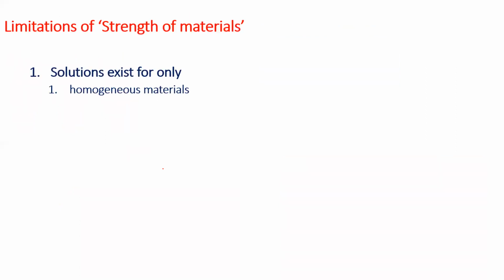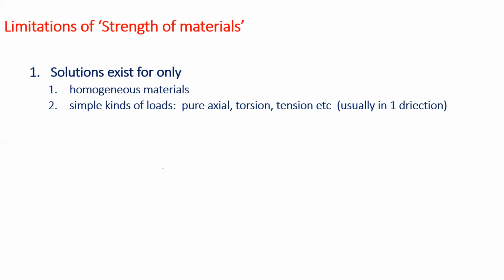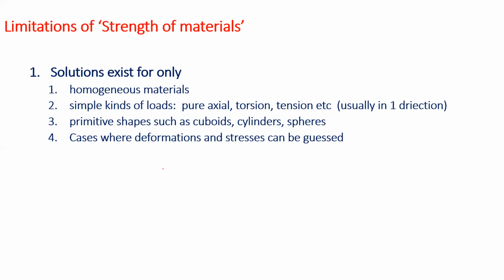Okay, so in summary, strength of materials does work for homogeneous materials and for simple kinds of loads, and you do work with simpler shapes. And in most cases, when I say cases where deformations and stresses can be guessed, we know upfront what is the only non-zero component of stress or strain.